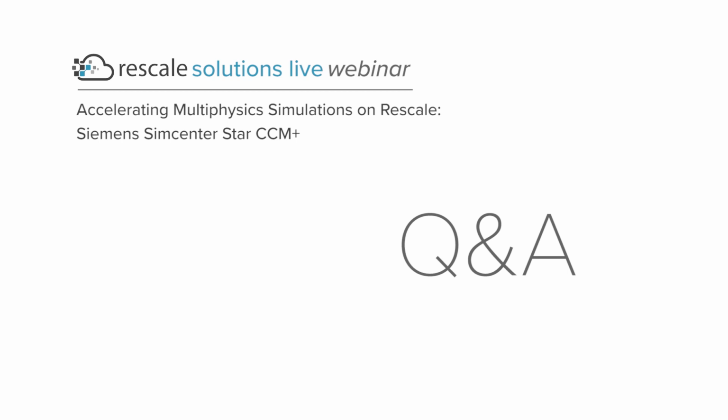Also, generally speaking, that's a very complex question, because it also depends on the physics you are studying. For instance, let's imagine that you have a simple flow, and these kinds of configurations scale very, very well, linear scalability. But for instance, in STAR-CCM+, when we add a Lagrangian solver, then the scalability is not exactly linear, although the Lagrangian solver in STAR-CCM+ scales very, very well. So definitely we have some rules of thumb, but it really depends on the physics. And we always advise to do some tests. Since it's so flexible to do a test on Rescale, it's definitely worth running some tests to see whether your simulation is scaling well.